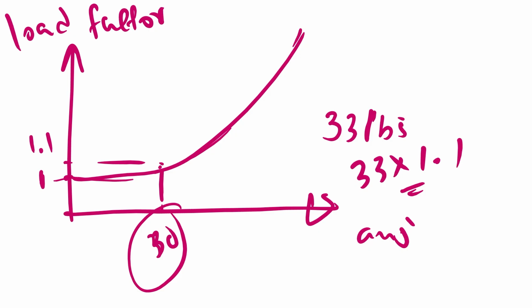At normal level flight we have a load factor of 1, but as we bank, the loading factor increases. So that's how we calculate. We need to know this relationship, and multiply the given load by the loading factor to calculate the corresponding load at that angle.